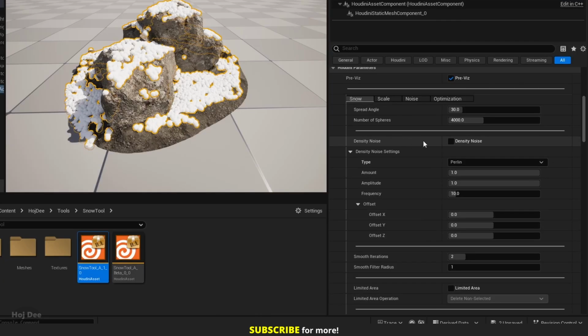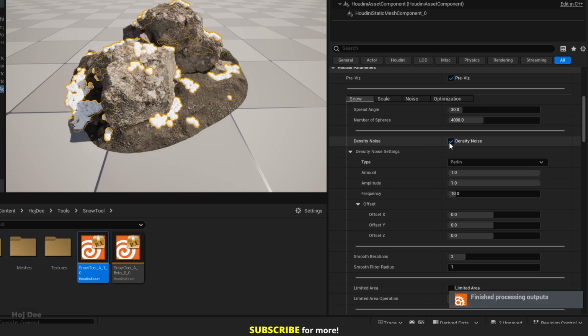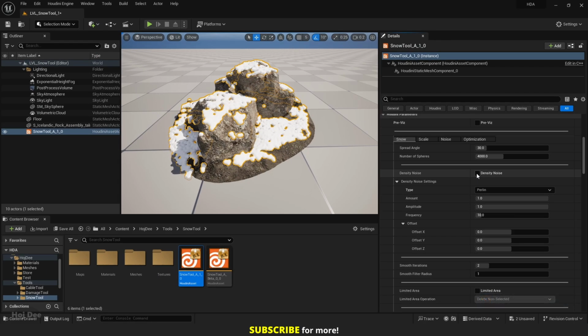Next we have density noise. It does as its name suggests. Right now we have snow everywhere on the asset within the spread angle we defined. Density noise removes some of the snow based on a noise pattern. Let's enable it. And some of the spheres are removed. Let's also check the snow mesh. And here's the snow mesh with density noise. Let's disable density noise. And here's the snow mesh without density noise.